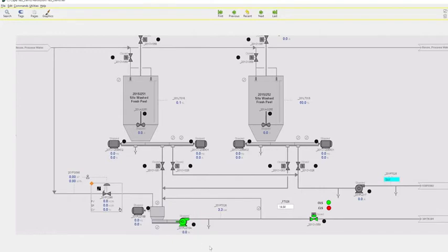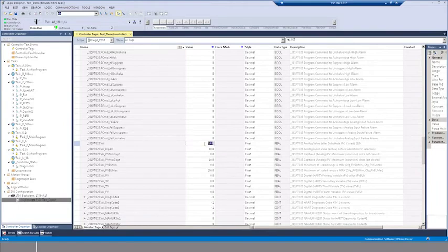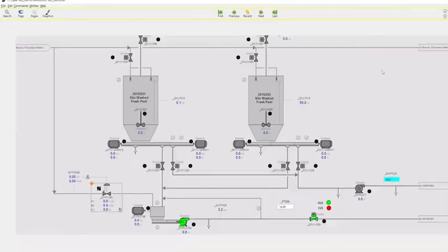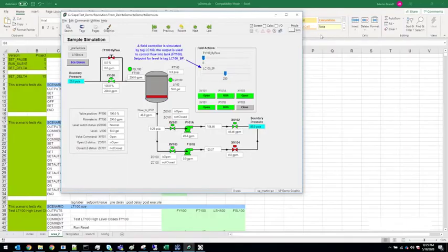In this example, the user tests the communication by pushing an arbitrary value in the pressure transmitter. For this example, the user can change the value to say 10. The user can then check the controller to verify that the value made it into the controller. Testing using VP-Link can be done by making ad hoc changes on the fly. We will now demonstrate some of the test compiler module features for VP-Link.